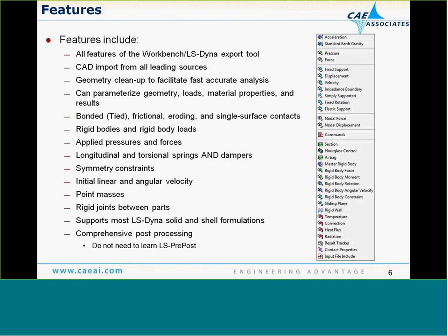You had to write out the Dyna input deck, run it separately, and then post-process using the LS-PrePost post-processor, not Workbench. So probably one of the biggest advantages of this new Workbench LS-Dyna tool is that you can post-process within Workbench. All import capabilities are still available.